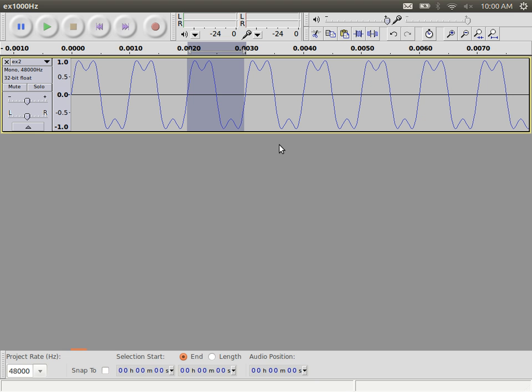Let's start simpler. What's the frequency of the first component in signal B? There are 2 components. What's the frequency of the first component? 2000 hertz. 2 pi ft, we have 4000 pi t, we get 2000 hertz. Second component, frequency, 6000 hertz.